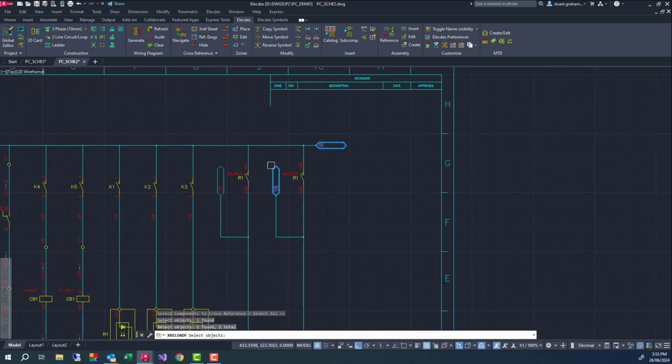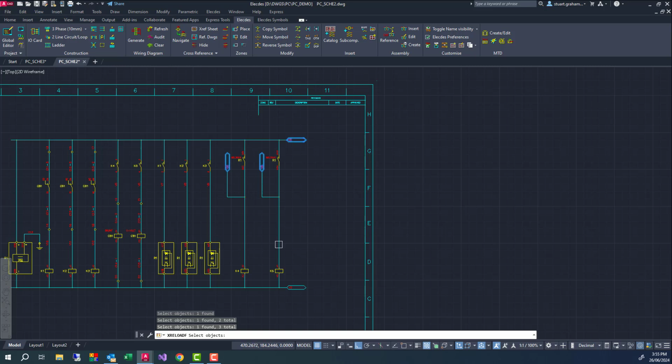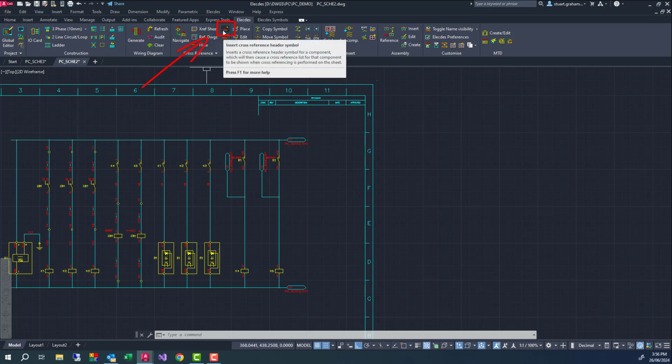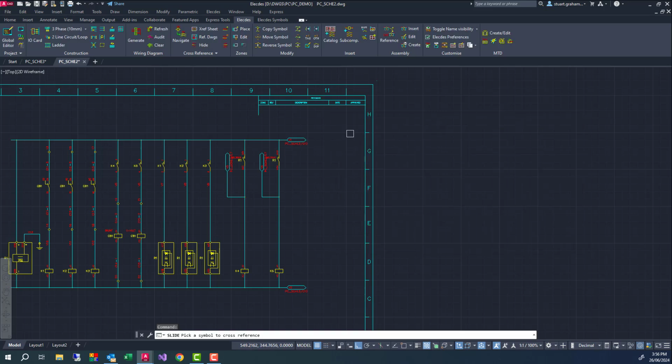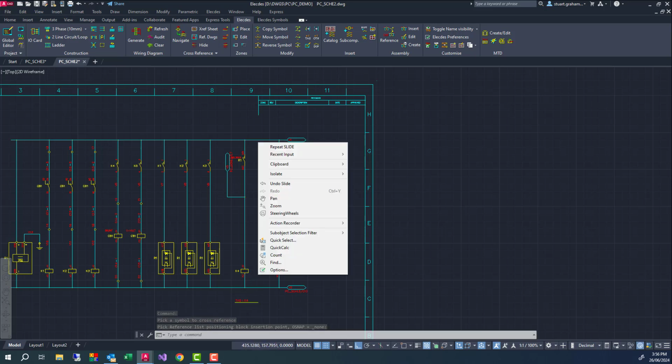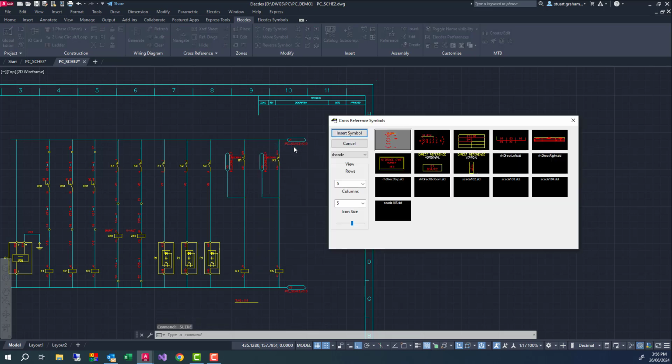While I'm at the other end of the extensions, I may as well use the cross-reference tool to insert the references on these wire extensions. Cross-referencing of families of subcomponents often requires a table to be positioned and created. I'll insert a table header. A table header needs to be linked to a component with a family that needs referencing. I'll make a table for the relays K4 and K5. I'll position the headers in the space under my relays.